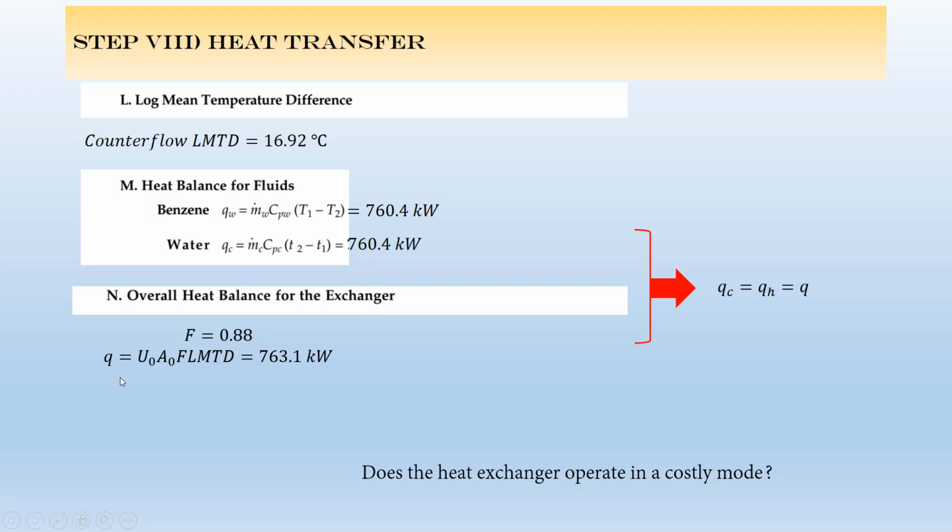The last thing is that you need to check the pressure drop. You need to make sure that the pressure drop is less than 70 kilopascal in both shell and tube side.